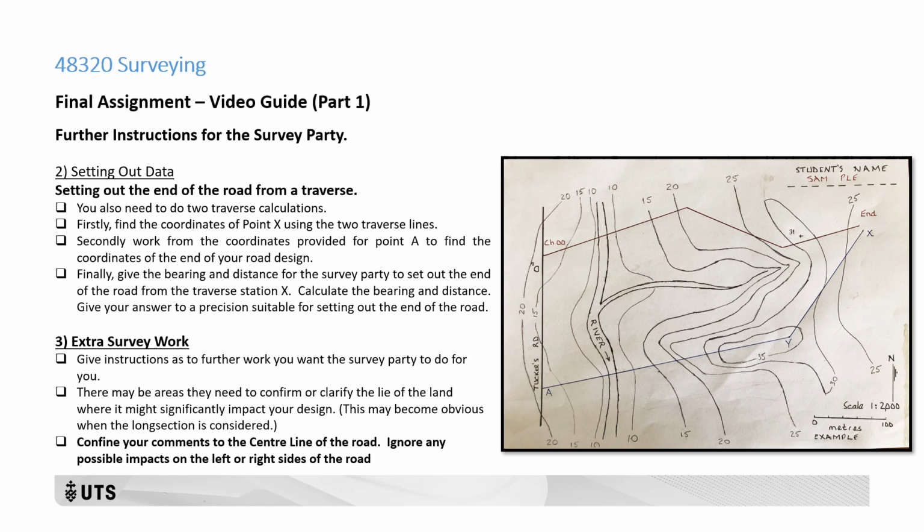Okay, the extra survey work. What do you want the survey party to do for you? Set out the curves, possibly do some long section work so you can get a better estimate of the long section over and above the contours. Think about how precise the contours might be. Might there be some extra data you want?